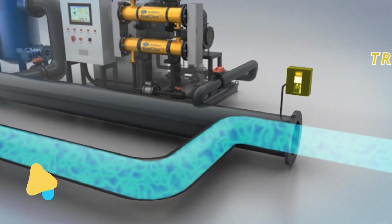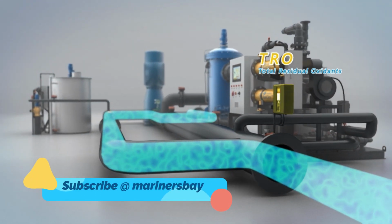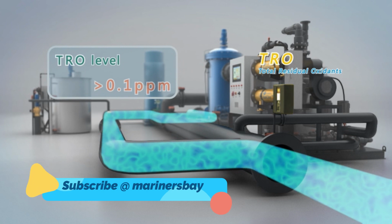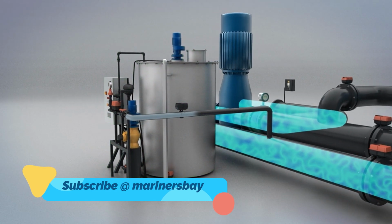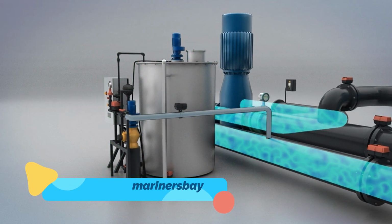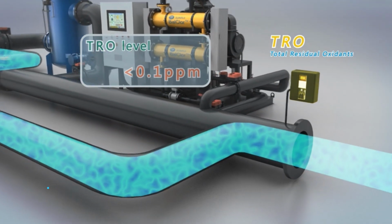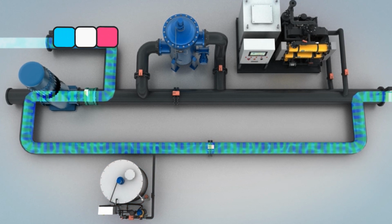The TRO, total residual oxidant, sensor installed at the outlet of the deballasting pipe will closely measure the concentration level of active oxidant. If the TRO level is higher than 0.1 ppm, the neutralization unit will be operated automatically. The neutralizer will be injected into the deballasting pipe.